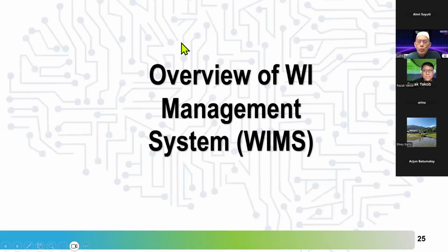Okay, now we go and cover the well integrity system. This is the subject where we discuss more about how this application will help us to really manage the well integrity of the well throughout the well life. So we start, if possible, from drilling a well. We start to record the information on drilling a well, how they do the cementing job, where the top of cement is, and then how the casing is placed in place. Was there any torque or any obstruction on going down? All this will help us to really improve our understanding about the well integrity, from drilling.